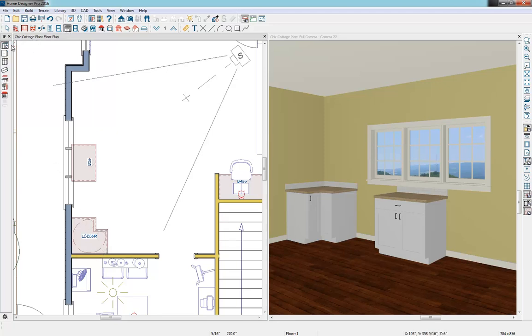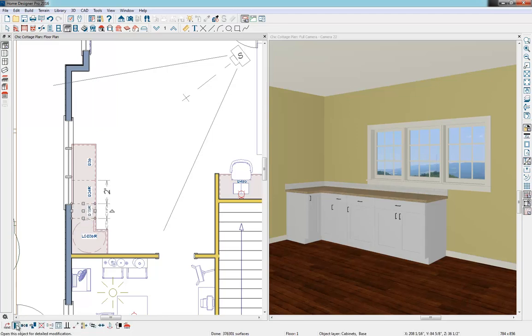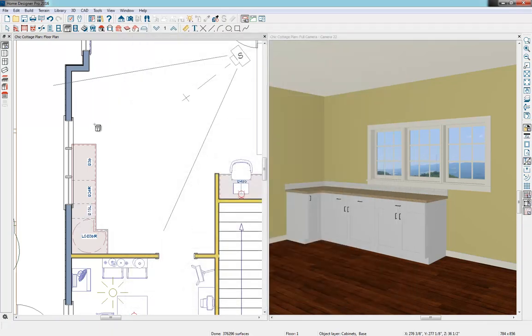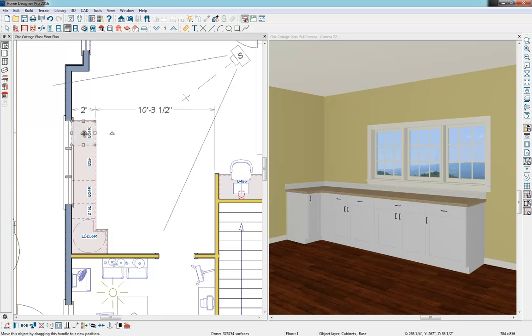So let's get back into our base cabinet, and I'm going to drop in a few more here. So we'll have a cabinet kind of spaced there to place our dishwasher. And you'll notice when it becomes a smaller area, it will automatically resize. So this space is 15 inches. You can tell that by the label that's created there. Single click to drop that in. And I'll just open this one up quickly. We're going to just change our door from right door to a left. And on the other side here, I'm going to modify this one down to 12.